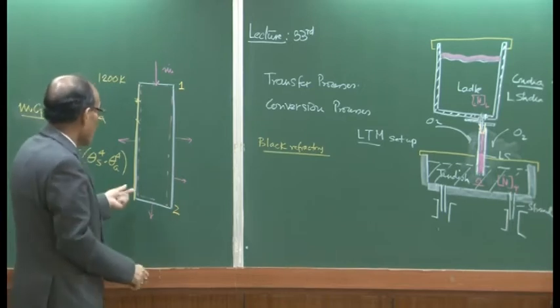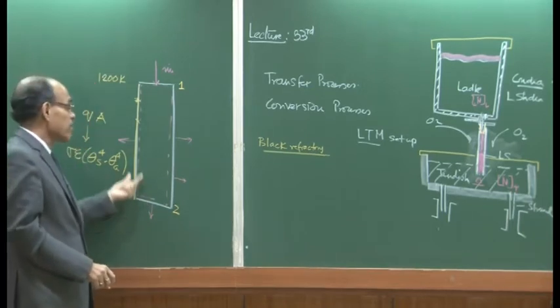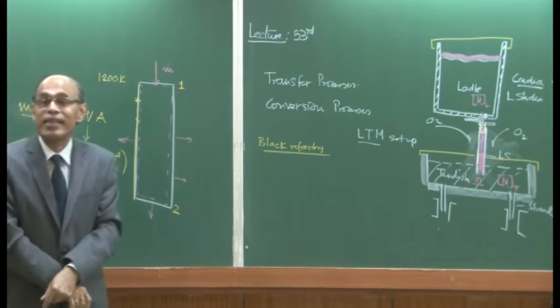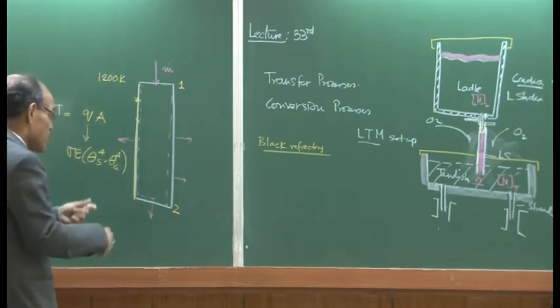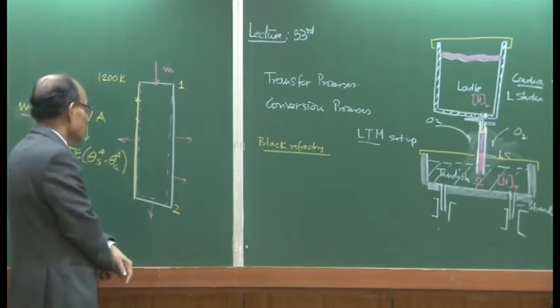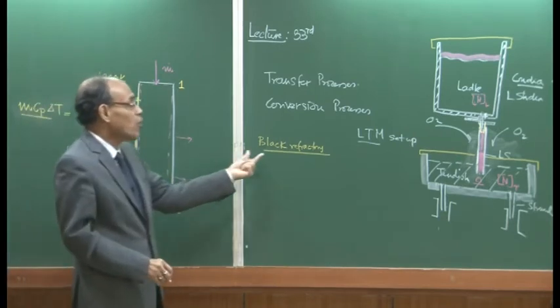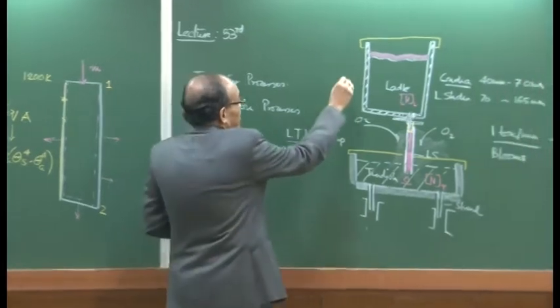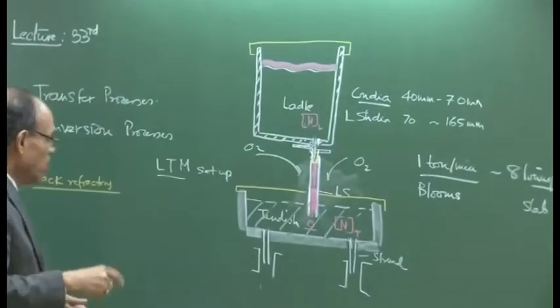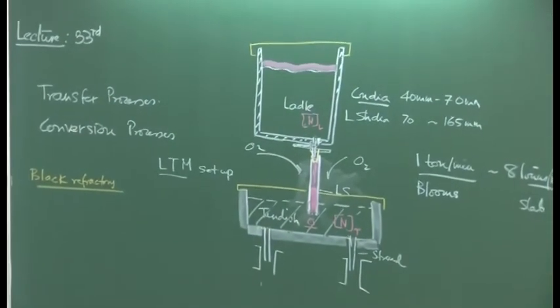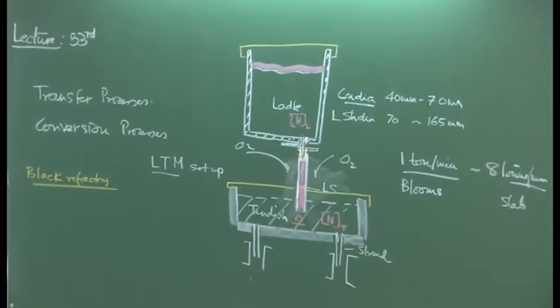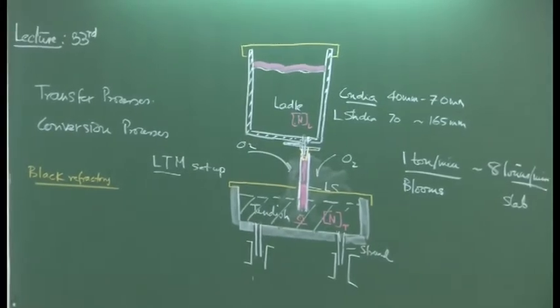And the composition of the shroud refractory, as I have indicated, is highly basic, which has a large resistance to heat flow. It is a good insulator, and in industrial terminology, while we say that the ladles are lined with bricks, these are not brick refractories, okay? These are black refractories, they are prefabricated structures and so on and so forth.